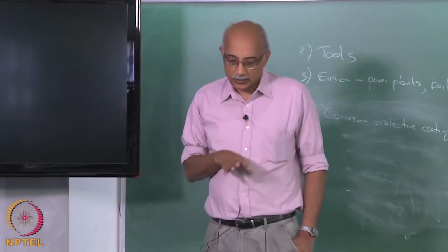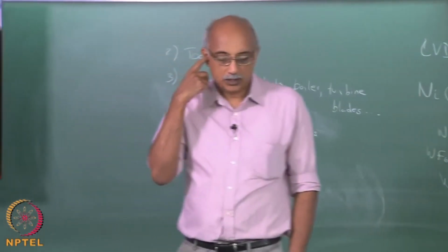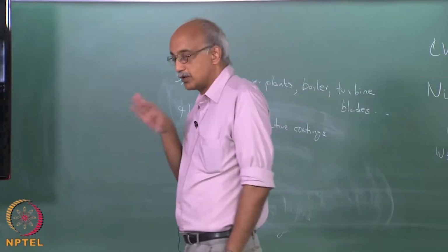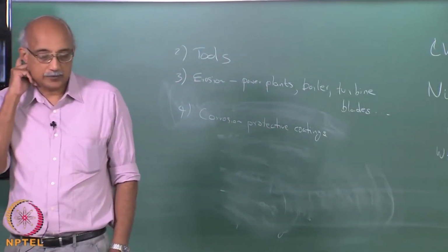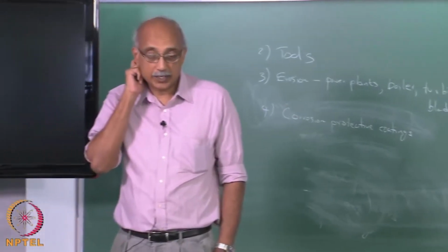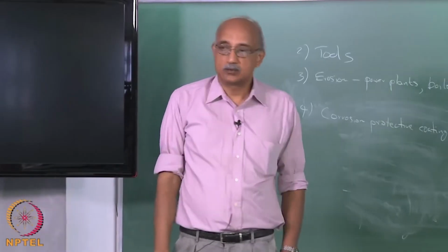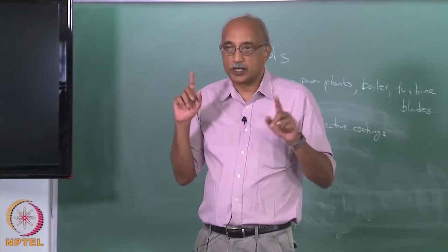And in fact, if you look at the turbine industry in general, they do use steel alloys rather than stainless steel alloys in order to minimize the cost, but they have to immediately deal with corrosion. So, the lifetime of these steel components can be quite low. So, what you really have to do is use what are known as super alloys.